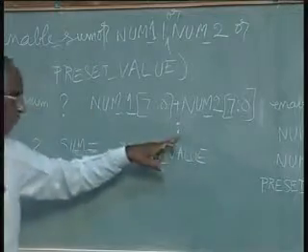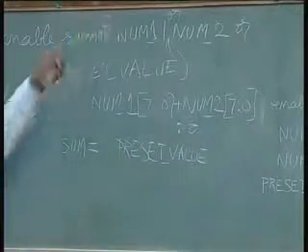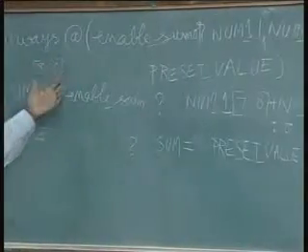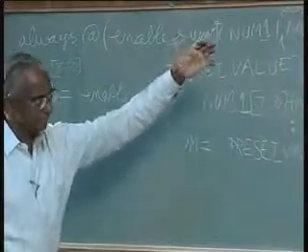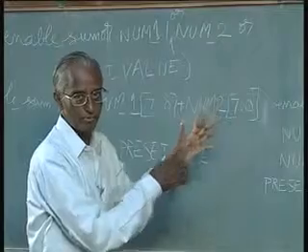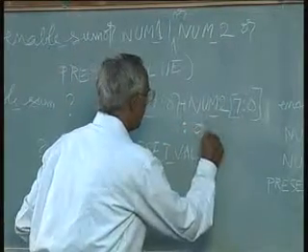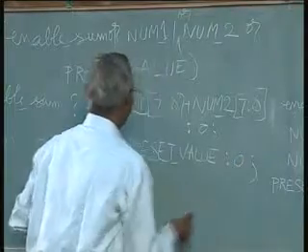So we will have to put a colon and then put just 0 at the output. If the enable is not valid, I mean it's not asserted, then we need to put just 0, because we just want to make a distinction whether it has gone through the actual process or not. And similarly here we need to put 0 here. So,